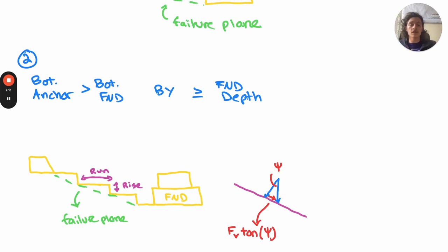In both options, the soil shear failure plane is sloping downhill toward the river. In the event of failure at this plane, we would need to analyze the forces on a soil component. As you can see, at this angle, a portion of the entire abutment weight will contribute to the shear stresses on the soil wedge, just like it will contribute to that downhill sliding, which is causing the friction that's causing shear at the soil interface.